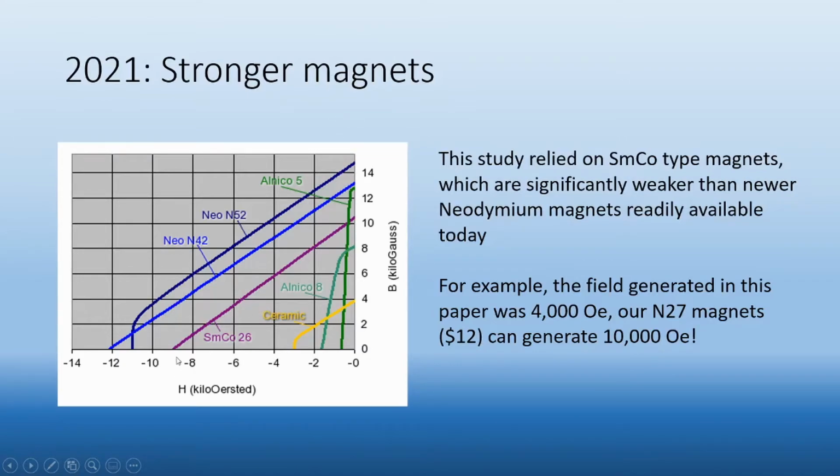There are different constants that people use to describe magnets, and it makes it pretty confusing because sometimes you'll get a rating for one magnet that's given in kilo-Oersteds, which references this value, or sometimes you'll get something that references this value that's given in kilo-Gauss, but you can't exactly convert it without knowing the hysteresis curve of that specific type of magnet.